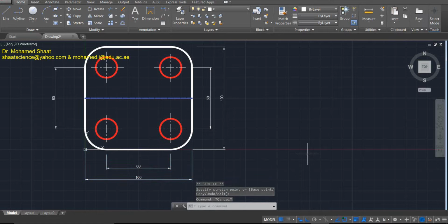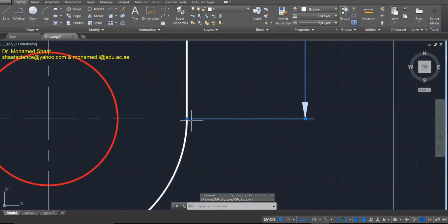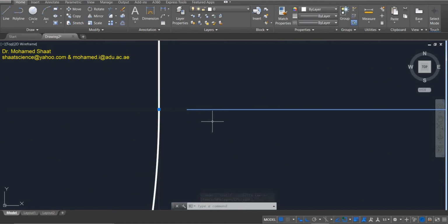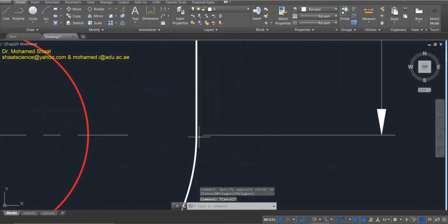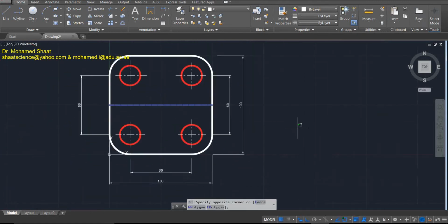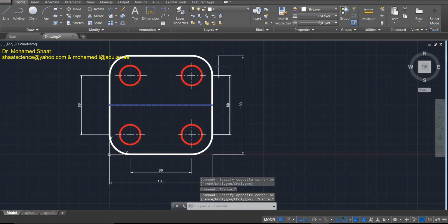So one of the standard things is that the extension line shouldn't intersect with the object. Also, there should be at least some space between the extension line and the object itself. Like this one, as you can see, the extension line is already coming directly. There is a small distance here. This is according to the ISO standard, but even this won't be clearly seen, because in this view, to me, this extension line is already intersecting with the baseline or the object line, right?